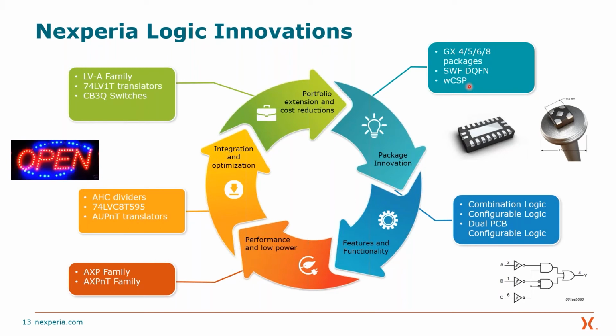So those are some of the package things which have occurred. Other things which have occurred too is that the family of logic continues to grow. You know, all of the part numbers in logic are defined. The 7400 is a standard part number. The 00 always means the same thing. It's a NAND gate, whatever logic family you're looking at. Well, we continue to add new parts to that family, primarily by combining functions together that were never available before.